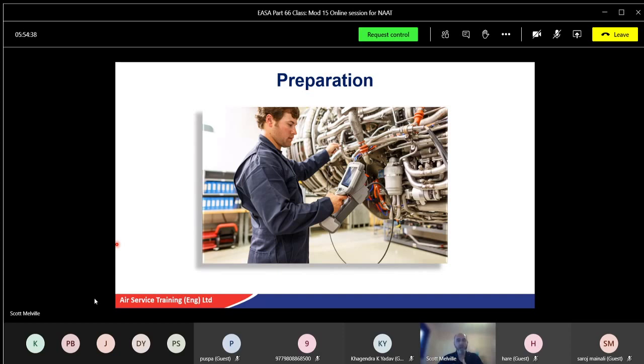Again, sometimes you might find something you're not sure about. Different people's vision differs, and although you can refocus the lens, it's worth getting a second opinion. You think, I'm not sure if that's a crack or is that a bit of dirt, get somebody else to come in. And maybe get another person, get 3 opinions, because if you make a decision, oh, that's a definite crack, and you take the engine out and it's not a crack, you've just wasted a lot of time. And I've had that before.